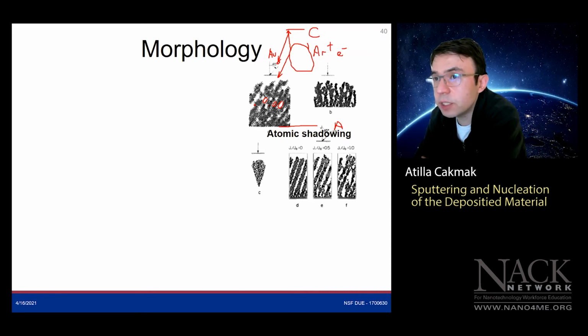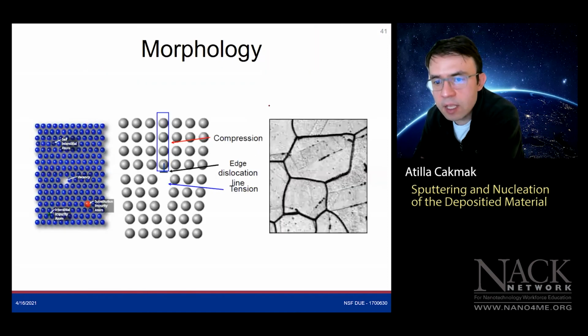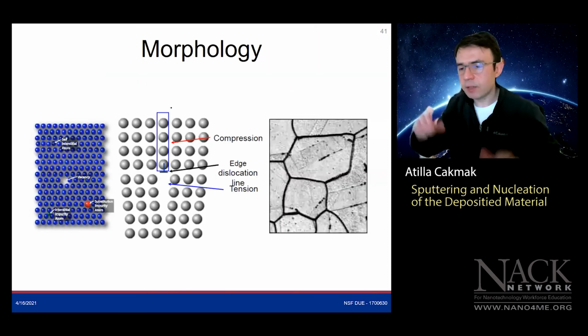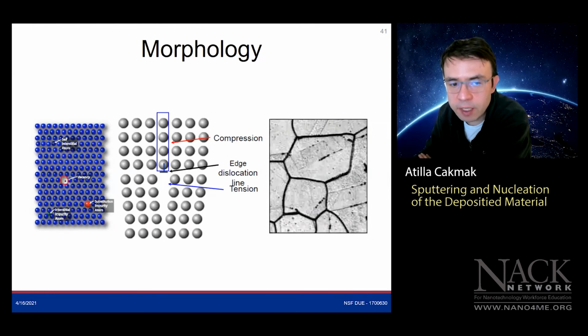So it's going to be really degraded from the metal that you're aiming for. The resistivity will be much higher if you measure it. People talk about the Thornton zone model, but we're quickly going over that. In the end, it's going to cause these kinds of vacancies. The crystal structures will be formed, like you can see the vacancy, and those vacancies will be very easy to oxidize, okay?